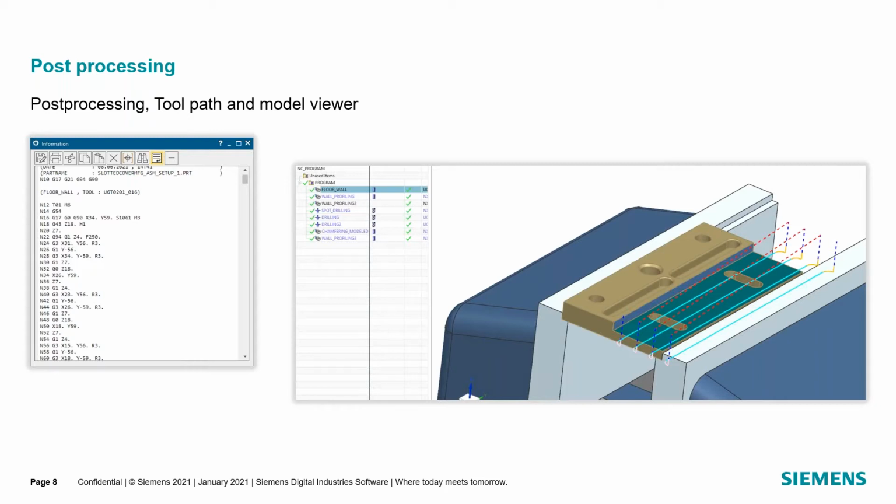So that's where a digital twin of the model can be prepared and then validated before it is produced on the machine. This is a journey wherein you can validate and review your toolpath, compare your toolpath, analyze how much cycle time it is taking on the machine, and even optimize the toolpath. Those are the manufacturing functions. Once you create the toolpath, let's say it is taking 10 minutes, but there are some algorithms with which you can optimize the toolpath. There is an optimization algorithm with which you can even compress your toolpath by 30%. These kinds of techniques will definitely help you optimize your toolpath and run your machine effectively.